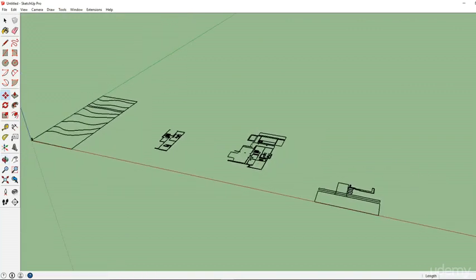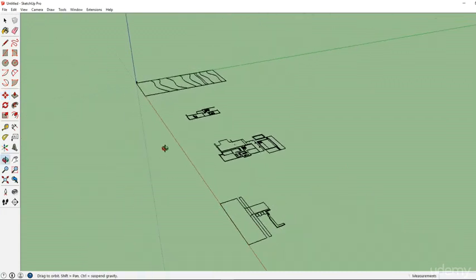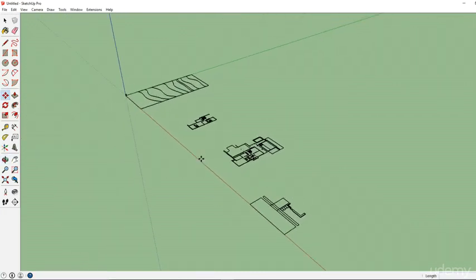There's a command called flatten in AutoCAD that you can use to flatten your plan so that everything stays on that 0 axis, because we do not want any of those 3D elements in this drawing.